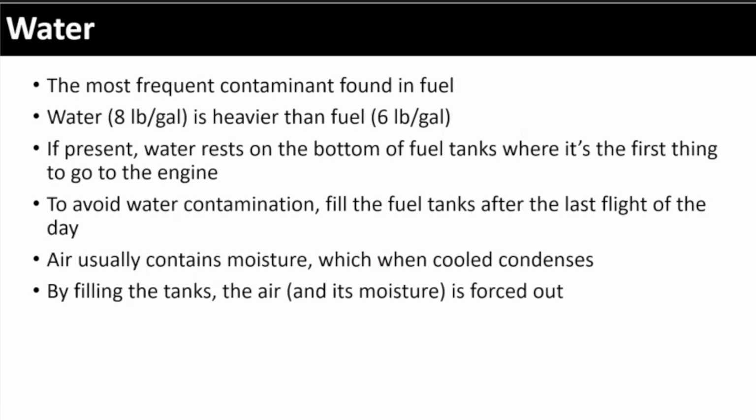Okay. Couple of ways we try to avoid that. Fill your tanks at the end of every day. Don't let the tanks sit empty in the hangar or outside the hangar overnight, because you're just giving yourself more chance of having that condensation water in the tanks. Fill it, make sure you're looking. When you test the fuel, always test the fuel. I'll get to that in a minute. Do they have a water separator? Not a water separator, they have strainers, which will hopefully bring it out.